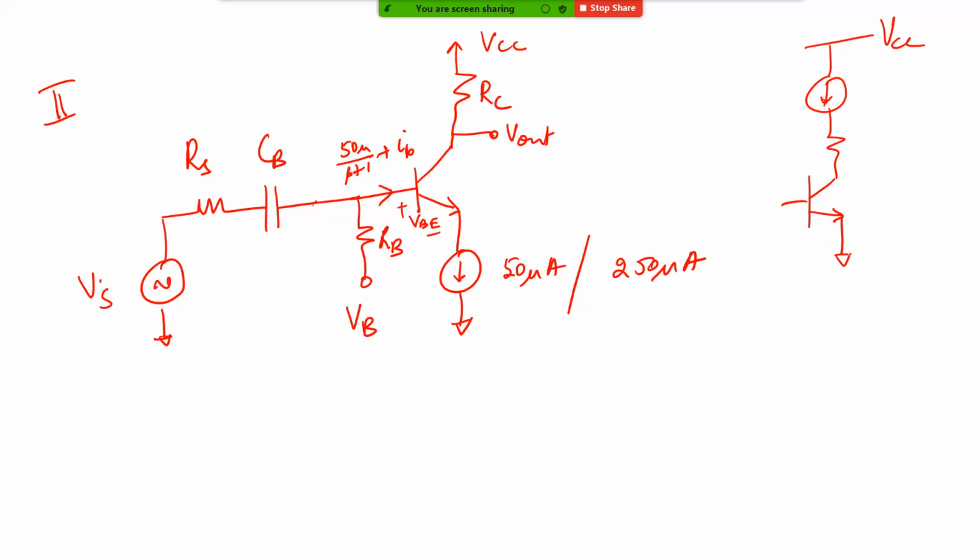Can we do that? Yeah, you can do that, but the way in which you implement your current source will be a little different. When we come to current source implementation, you will see that this will need a certain Vmin across it. So that is going to eat your headroom of your amplifier. But there's nothing wrong, you can do that.